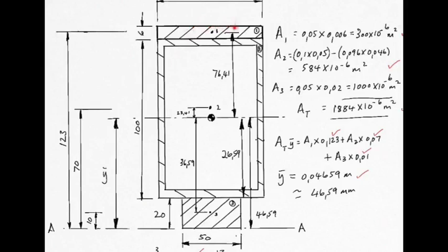That is going to be the one that you use with the bending formula, because these fibers are the ones that are furthest from the centroid. These are closer, so they're not going to be the problem. These fibers here are going to see the maximum tensile or compressive stress when this beam is bent or loaded such that it is bent about this axis, which will also be called the neutral axis, by the way, the axis where there's no stress.